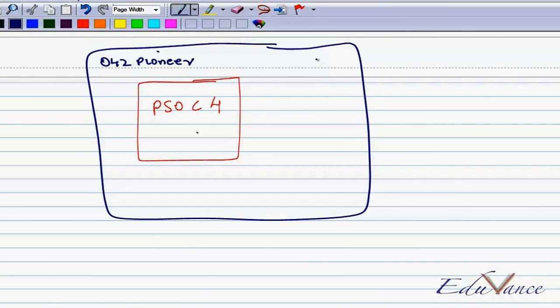So on your board you have a tri-colored RGB LED. So we have the R, the G and the B with a common anode. So this is connected to VDD. So what we would be doing is we will be using the PSoC 4 device to connect to the R component of the LED.